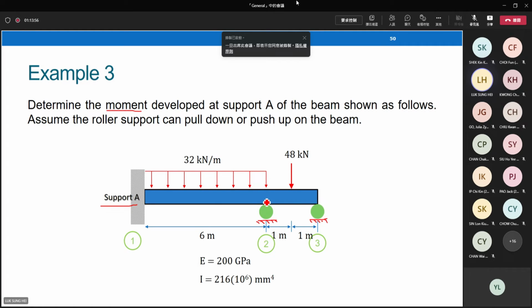So how to deal with this problem? Different people may have different discretization skills. The procedure is quite systematic. You first conduct discretization, number the nodes and elements, and then find out the element matrix, formulate the force displacement equation, and then solve it. The procedures are always the same. But the problem is, how to discretize these structures?